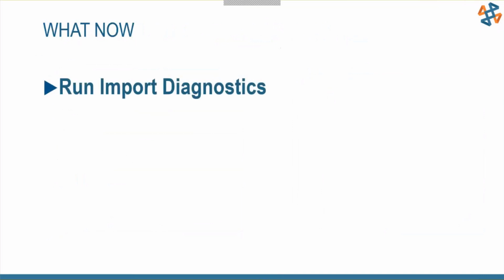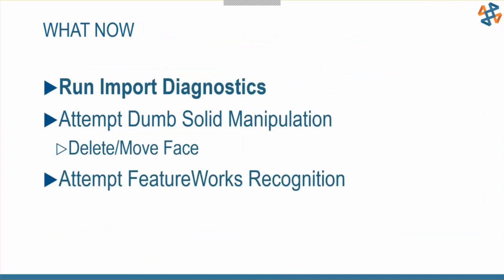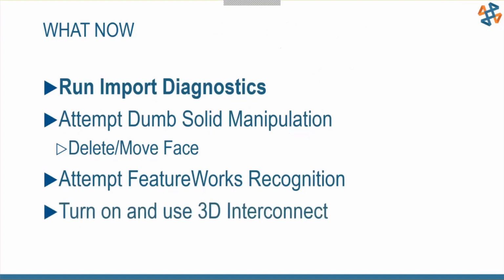So a lot of times we'll get the question of what now? What can we do now? First and foremost, give a shot at running import diagnostics. You might find in an area where you have problems that it might be caused by bad, faulty geometry. Attempt some dumb solid manipulation. Try using delete and move face. You might just like it. Then attempt a FeatureWorks recognition, so try and go through editing an imported part. And turn on and use 3D Interconnect for your workflows.